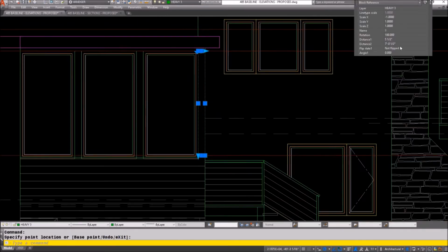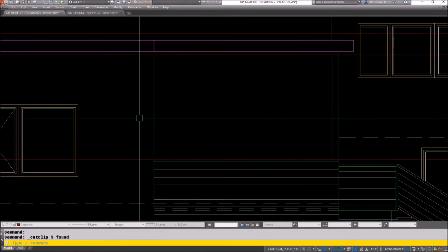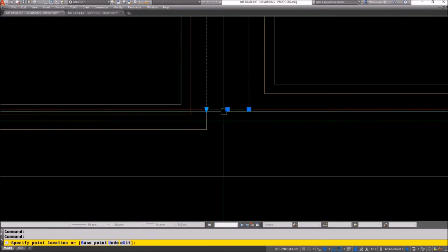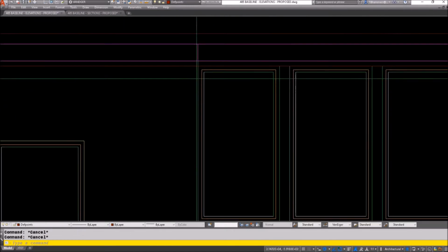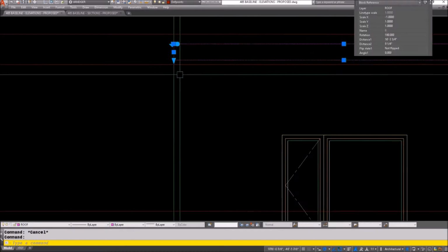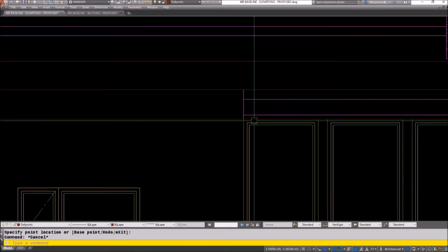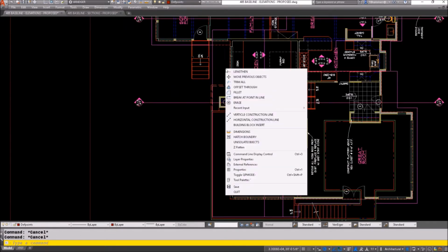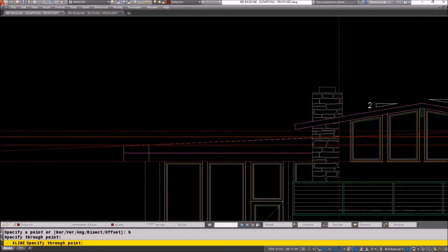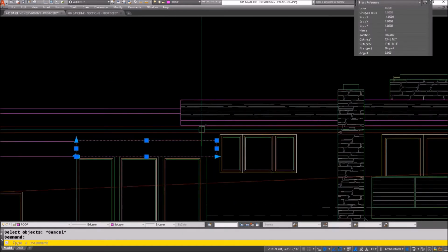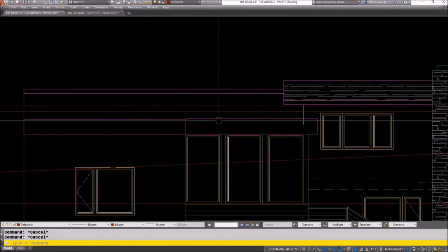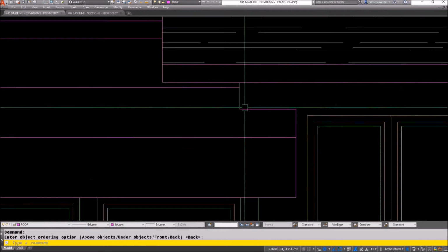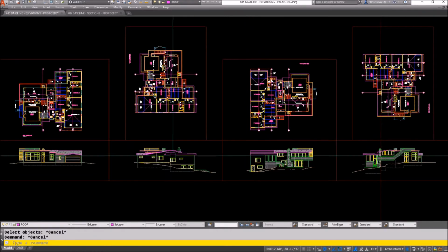This is those windows. He wanted me to screen those. So what I did was explode my windows. First of all, I made them the right size. So this is me entering all the data to make them the right size. You can see me dragging the grips on my dynamic blocks to make those the right size. What I did with these windows was I used a hatch in there and made a real faint hatch with some screenage. I hope I covered everything he said. He'll let me know. I just sent this off to him a couple days ago. Maybe it was yesterday. No, it was 2 days ago.